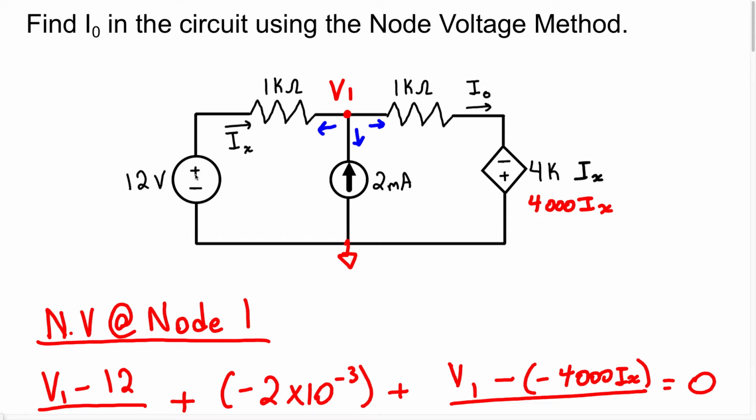It is flowing away from the voltage source to node 1. So even though we assumed when we wrote our node voltage equation that the current was flowing away from the nodes, that's just something systematic that we do. When we want to find the equation for that dependent variable, we're going to look to see how they labeled that dependent variable, okay? So because they actually have it going towards the nodes, that's how we're going to treat it.